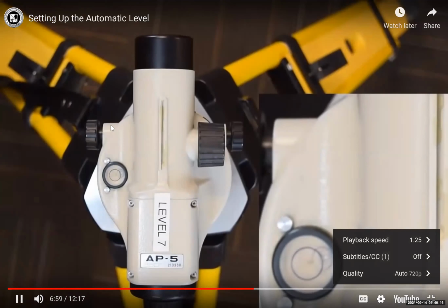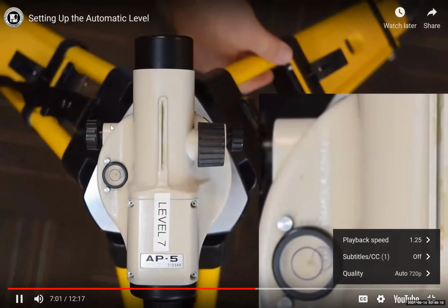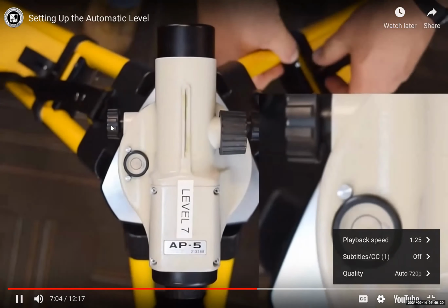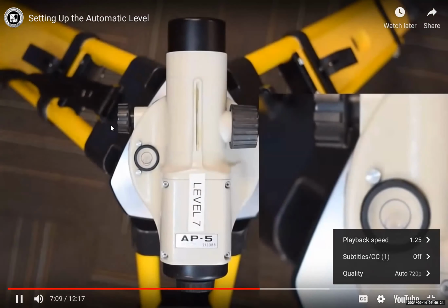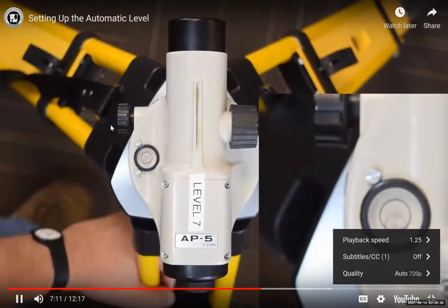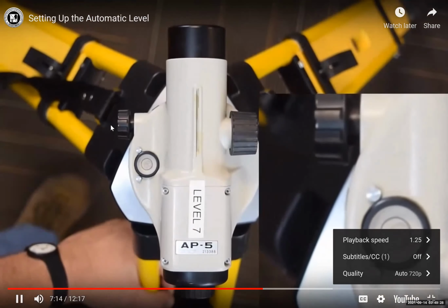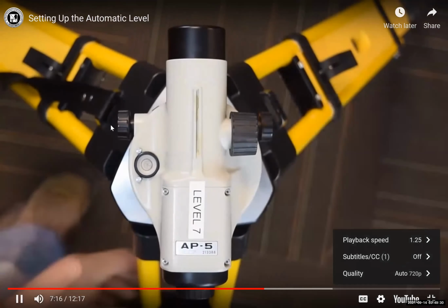Therefore, I'll stop adjusting the leg when the bubble lines up in line with another tripod leg. Then I'll shorten that leg to move the bubble into the circle. One more adjustment with the first leg moves the bubble just a little bit more. Now, this is the end of the coarse leveling phase.